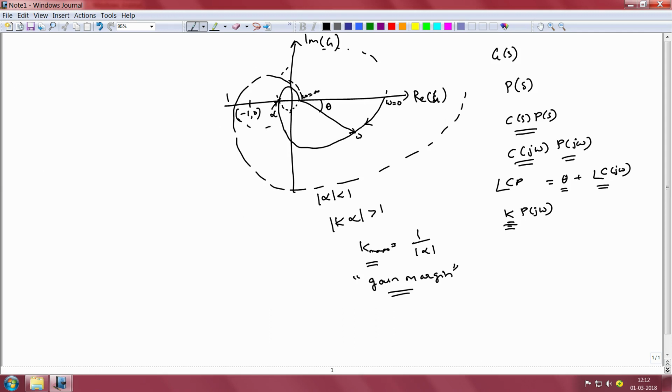Let us say at some particular frequency omega, if the controller adds a phase lag of minus theta c, what would happen to this complex number? What would happen is that this complex number would get rotated in the clockwise direction, so that the net angle that it makes now is no longer theta, it is going to be equal to theta minus theta c. So we see that the effect of a controller that adds only phase lag to the plant transfer function is to rotate the Nyquist plot at each point by a certain angle that is dependent on the phase lag added by the controller.